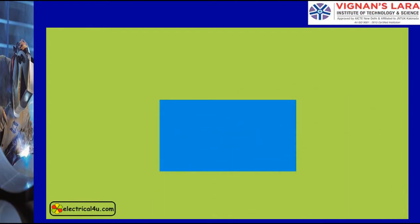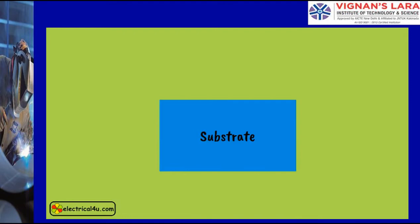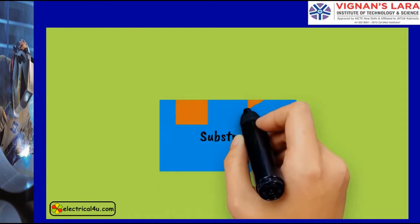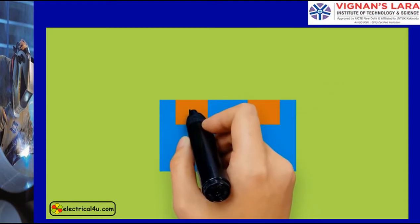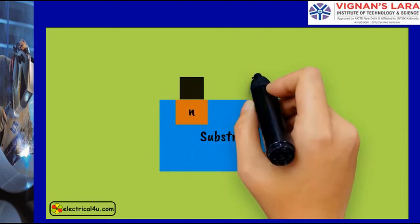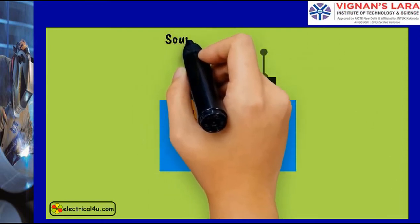This block will be your base for the MOSFET. We also call it the substrate, and the entire MOSFET we will fabricate on this base. Now two portions on the same side of this P-type substrate are made highly doped with N-type impurity, as shown in the figure. Source and drain terminals are brought out from these two N regions.